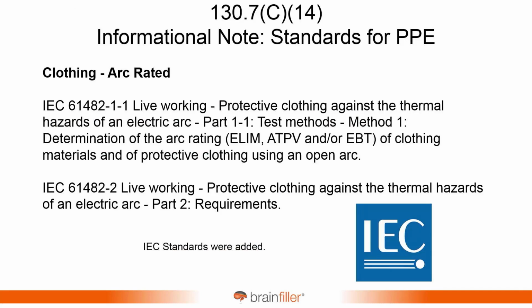There was another pretty significant change, and this one, I was somewhat involved with. Not so much in making the change, but let me explain what happened. Back with the 2018 edition, I mentioned how standards have been removed from the mandatory part of the text of 70E and had been moved to informational notes. So back in 2018, the ASTM standards for PPE testing were taken out of the mandatory part of NFPA 70E, and they were moved into an informational note.